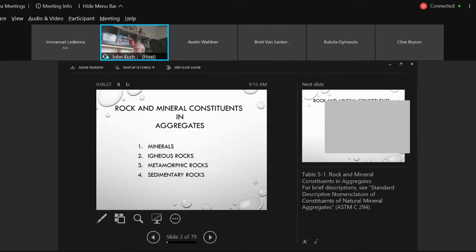Anyhow, coarse aggregate. Again, I'm going to go through these quickly. There's different types. You know, there's igneous, metamorphic, and sedimentary. Our aggregates here locally in Winnipeg are typically sedimentary with some igneous. If you go to Stonewall, the aggregates that we looked at last week, remember I said they were crushed limestone. That's what we have in Carsey. It's donated to us. It's donated by Lafarge, and they typically donate crushed limestone from their Stonewall quarries, 100% crushed.